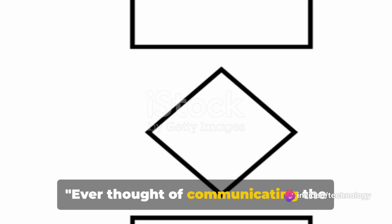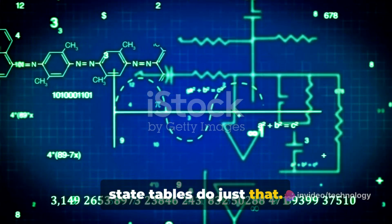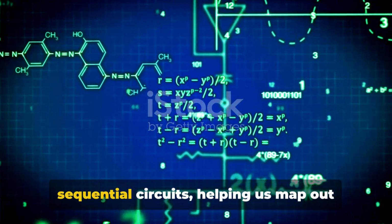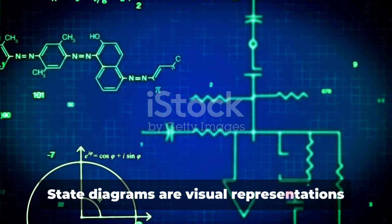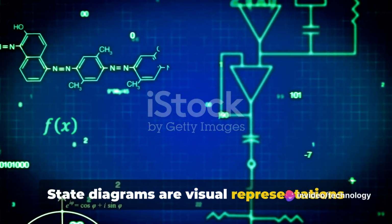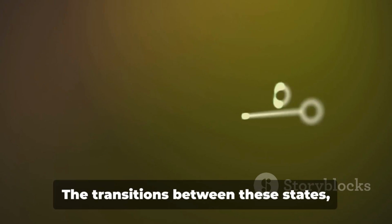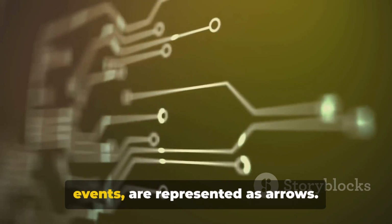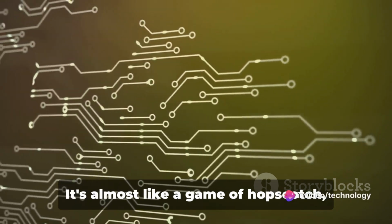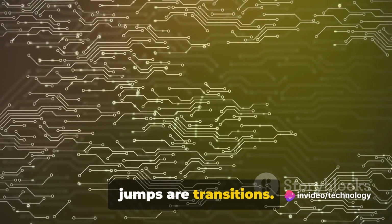Ever thought of communicating the behavior of circuits? State diagrams and state tables do just that. They're like the secret language of sequential circuits, helping us map out the complex paths of information flow. State diagrams are visual representations of the states in a circuit. Picture them as a network of nodes, each node representing a state. The transitions between these states, triggered by clock pulses or external events, are represented as arrows. It's almost like a game of hopscotch, where each square is a state and the jumps are transitions.